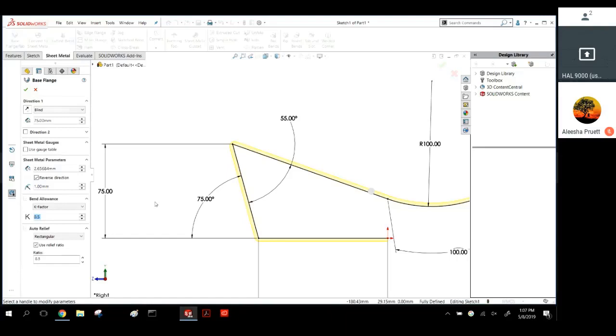A lot of times here at X, where I work, if we're going to produce something, a bunch of them, we're going to have an outside vendor doing it, and they don't really care about our flat calculations. You'll see that when I do the flat, it's more of just a reality check to make sure that my steel isn't running into itself when it flattens out.